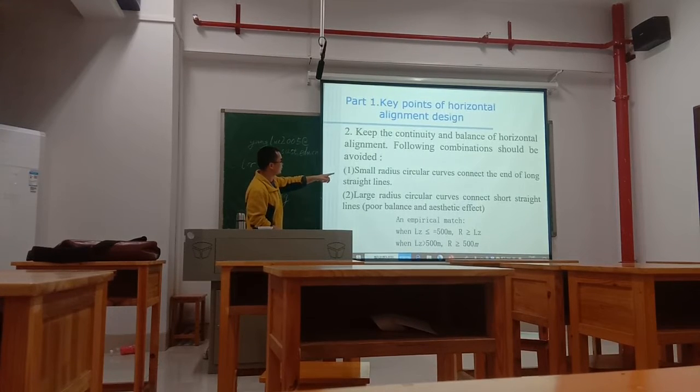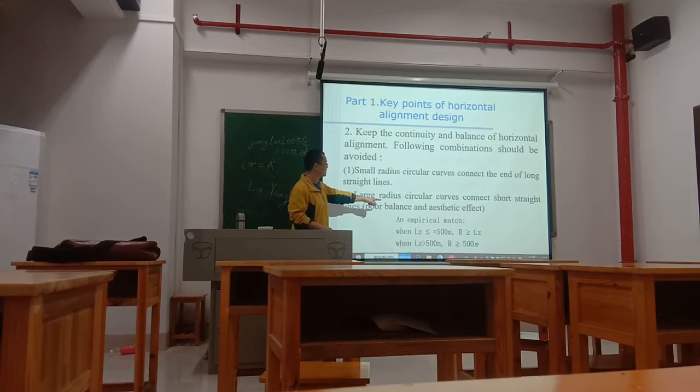Small radius circular curves connected to the end of long straight lines must be avoided. 2. Large radius circular curves connected to short straight lines must be avoided. Poor balance and deceptive effect.